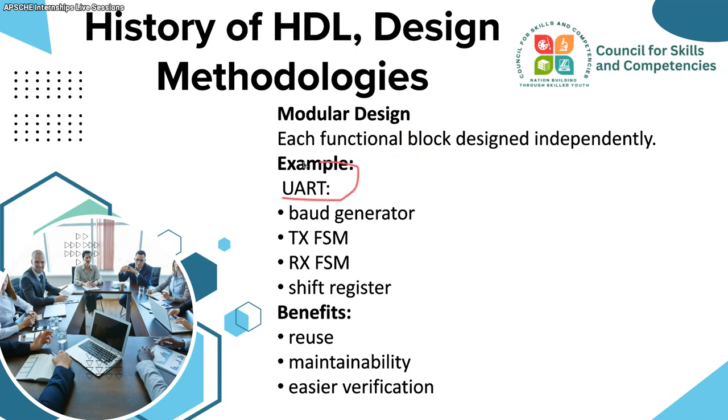The other example, inside the UART, you can generate the baud generator by some team, and a TX finite state machine for transmission. For that finite state machine, someone can generate it, and for the shift register, some other people can generate it. Okay, so we can go and reuse it. For UART1, UART2, you can go and reuse the things, and maintainability and easier verification, those things will be easy.